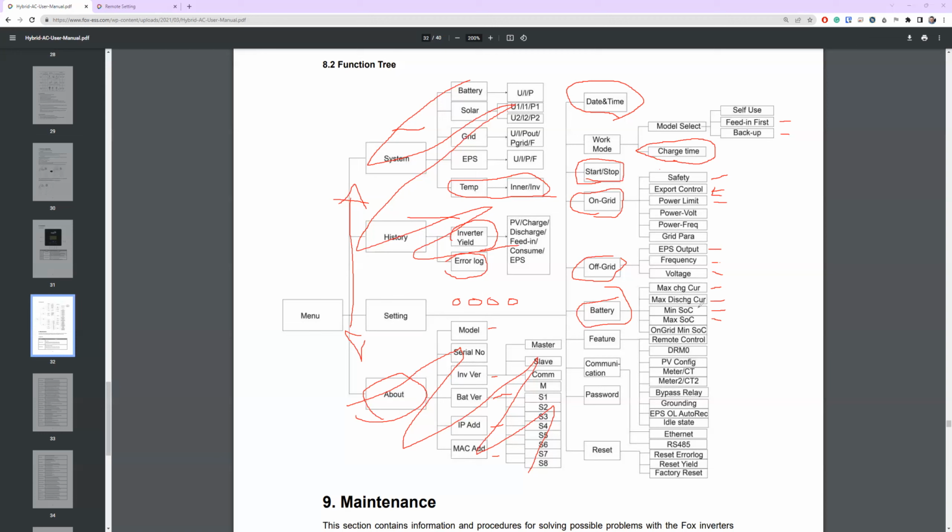Again, from everything that I've calculated based on the rate of the electricity costs, I think you gain more by using the battery down to 10% than dipping into the grid at those times. So it's the cost of the batteries and the wear versus the longevity of the battery. So really, for minimum state of charge, you should have it on 10 if you use the battery, and 20 if you want to be slightly more conservative.